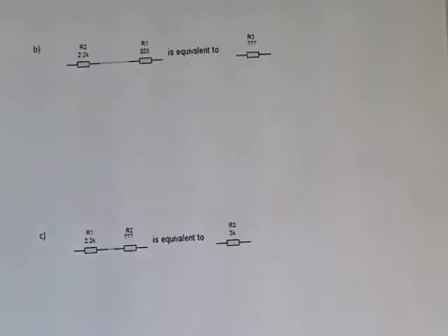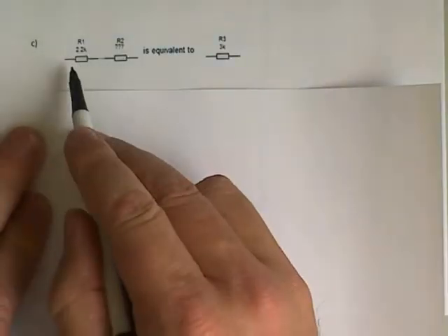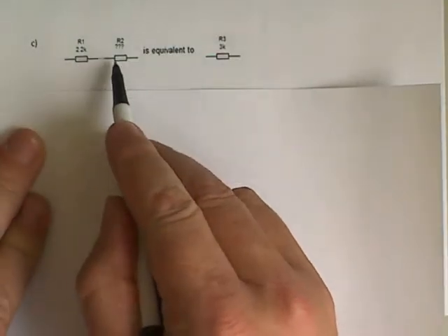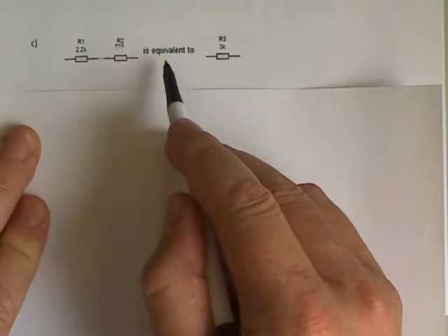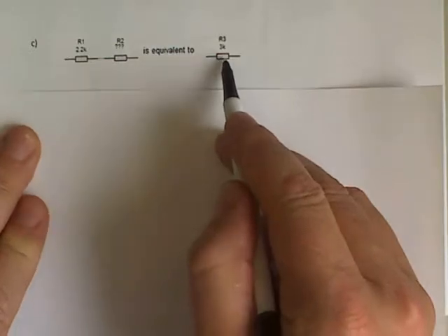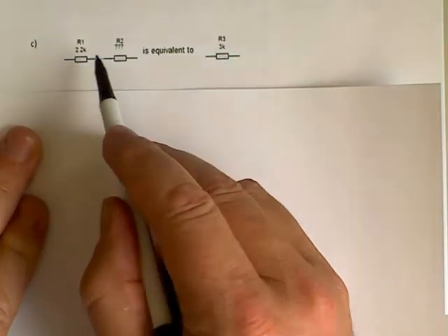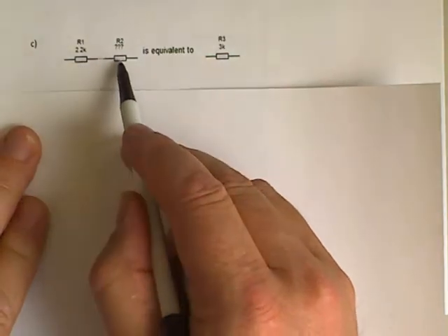Another example. If I have two resistors, then I want to have them in series to give an equivalent 3k resistor. One I have a 2.2k and an unknown value. Which value do I need?